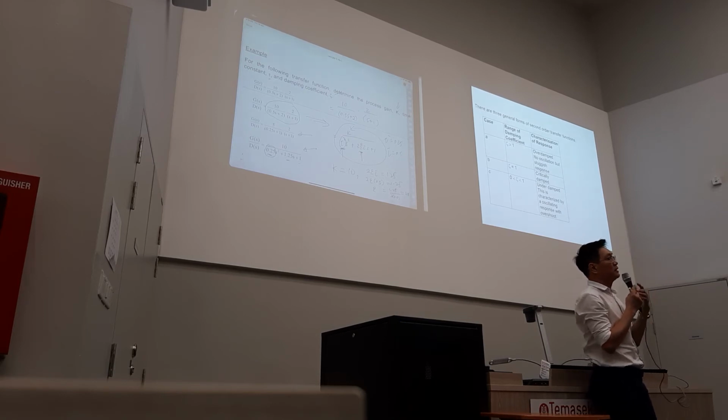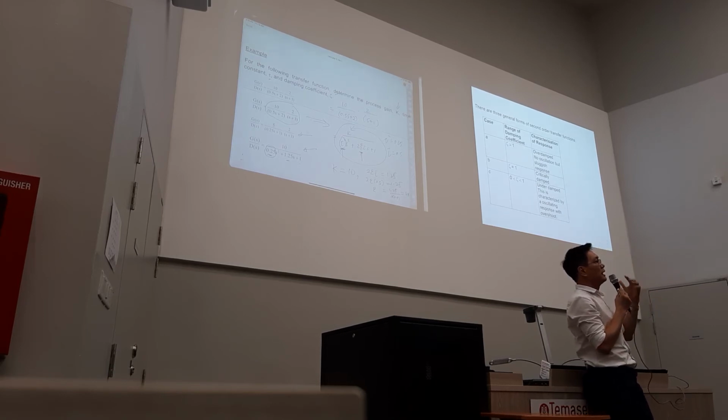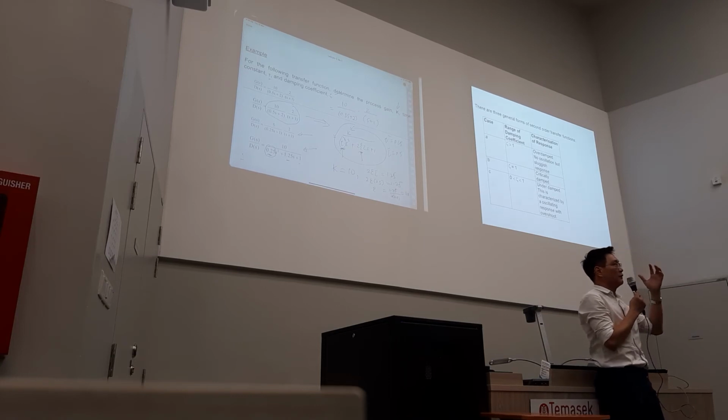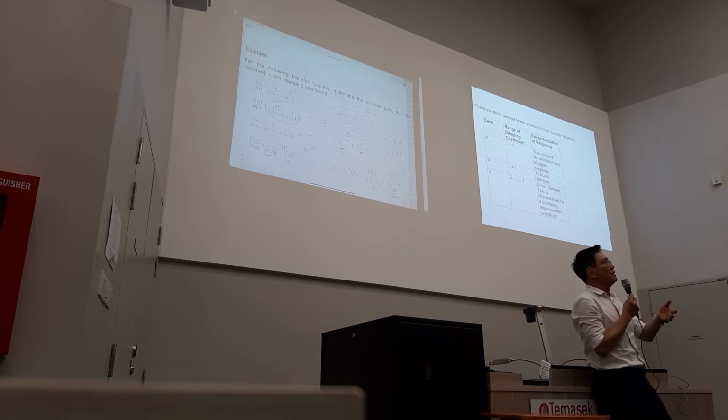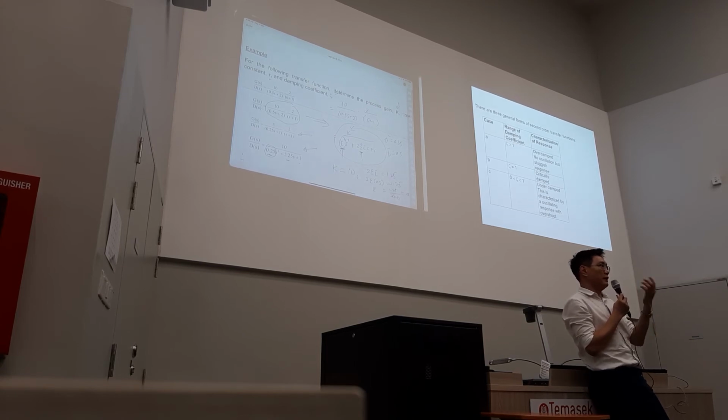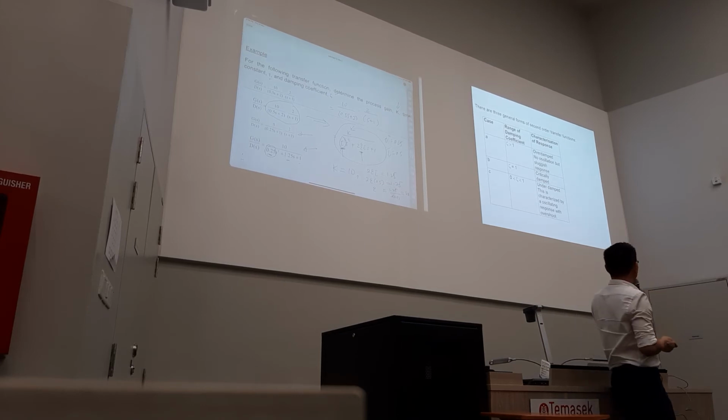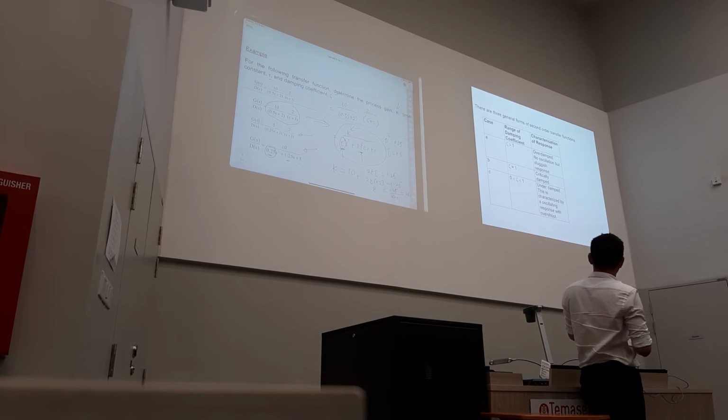And when the process dynamic is very slow, remember early on I mentioned to you all, I have a big tank and I have a small tank, right? So if I have a very big tank or very big pond, normally the damping coefficient is very big. So for cases like that, when I choose my instrument or I design my process, I can buy the cheaper one, or I can buy something not so high technology or sophisticated. I can save cost.